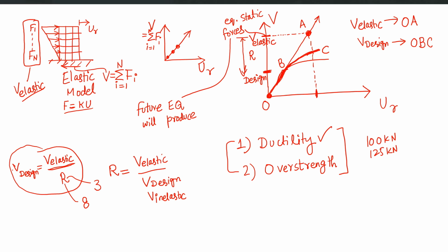the requirements of different structural systems. So again, I repeat the answer to your question. Whether your structure is going to follow OA or OBC depends on what forces you apply for the seismic design, on what forces you design your structure. If you design on V elastic, higher forces, your structure will follow OA. It will not even crack, but at the same time, the design will be very costly.